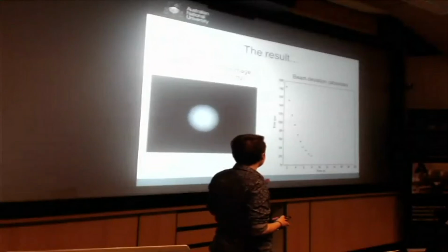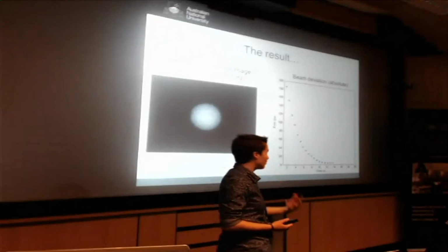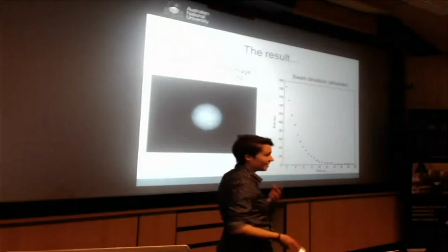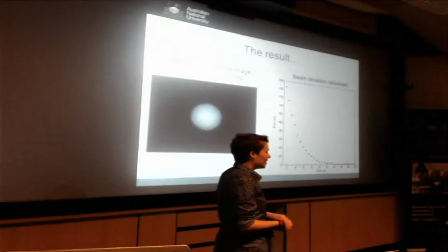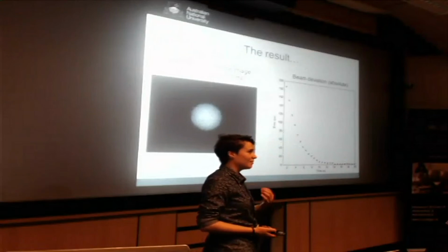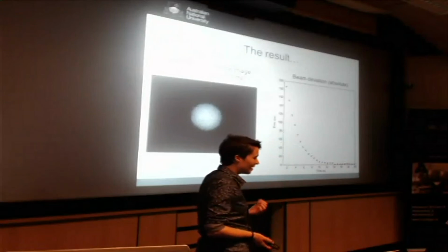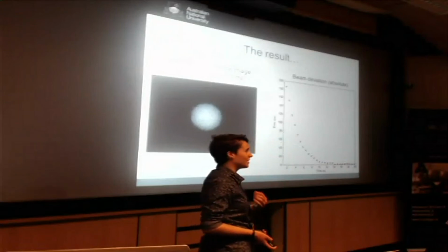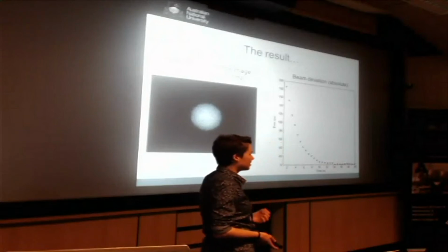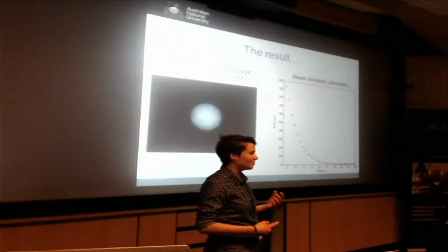So what I've done here is I've given the beam non-zero initial displacement from 0, and I've allowed my control loop to run. As you can see, the beam slowly gets dragged back to the center as desired. So it's working. I should also point out here, though, that the control system at the moment is limited to run at about a frequency of 1 Hz. This is due to an integration problem between the camera and the computer, which we hope to fix in the future, because a control system running at 1 Hz for this application really isn't that useful.